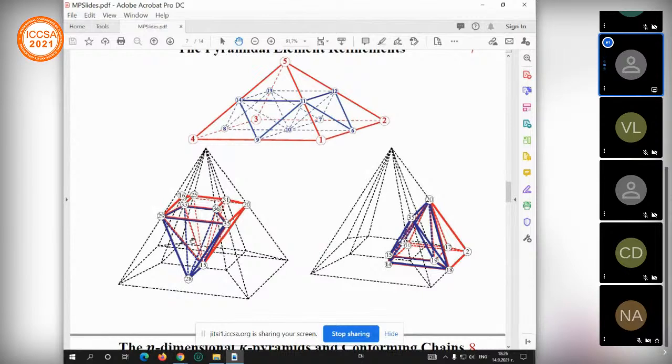The square pyramid is a transitional element in the interface subdomain between structured and unstructured meshes. Multigrid methods require stable refinement of all elements in the coarse triangulations. The optimal refinement strategy for the square pyramidal elements has been described by Ainsworth and Fu.